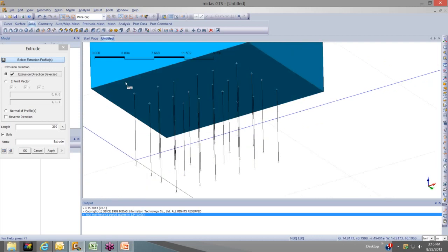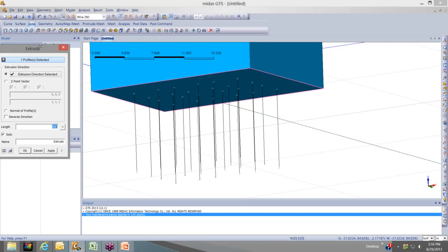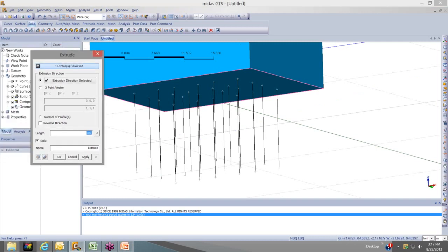When you're selecting the bottom layer here, or the bottom wireframe, just go to the corner, and then you have to navigate the cursor up to a certain edge where it'll select the wireframe. This can be a little tricky, as you can see. I selected it a couple of times, but I keep moving over it. There it is. So now, just create the length, which I believe is 0.6 for the raft. Check on the reverse direction, and just name it raft. Okay, there we go.